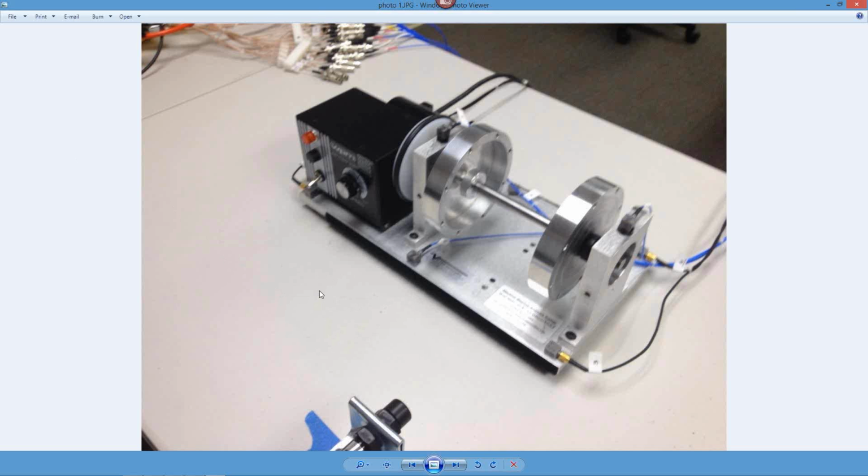So here it is. This is a rotor kit. It's got a variable speed knob here and an on-off switch. This is a little power supply. It's got a couple of rotors, and you can see that there are some accelerometers. These are triaxial accelerometers. There's one on each of the bearing blocks. There's 6 of them on the base plate. So a total of 12 accelerometers. Over here you can see the tachometer that's going to measure the rotating speed of this machine.